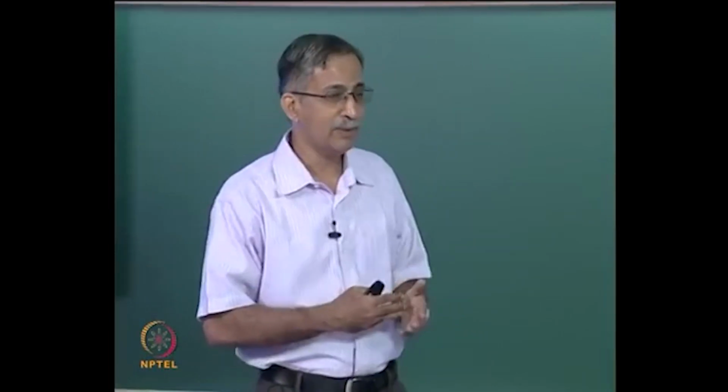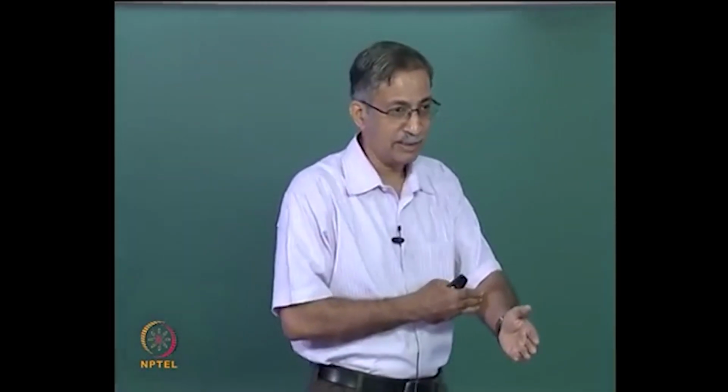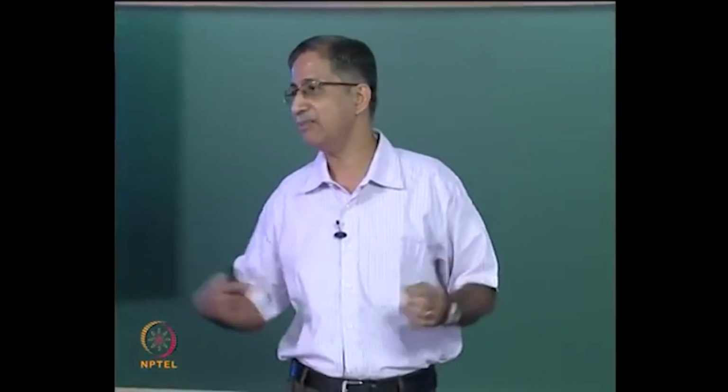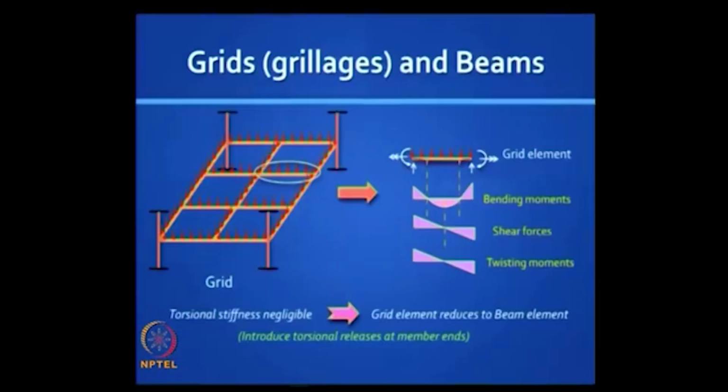So often you can assume that there is no moment transfer, and this is allowed by many codes. You can treat the beam as being simply supported. So if you make that assumption, the grid element reduces to a beam element.